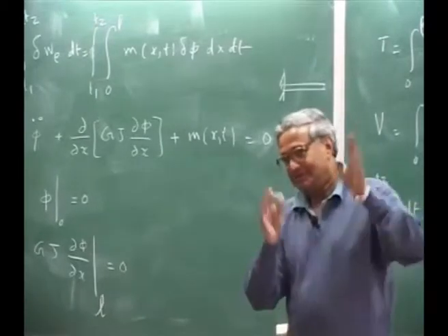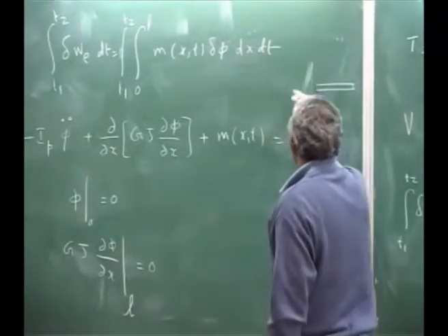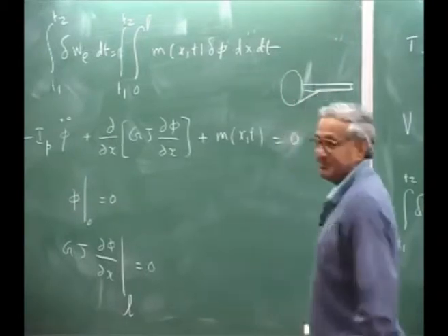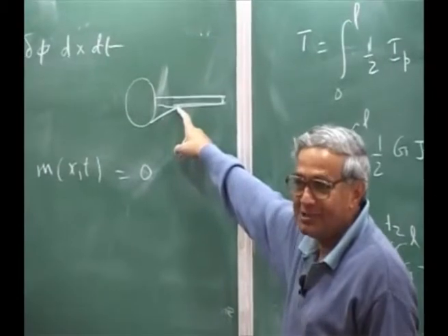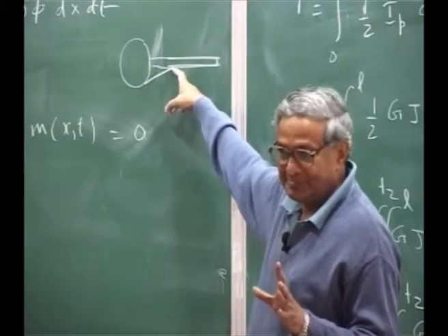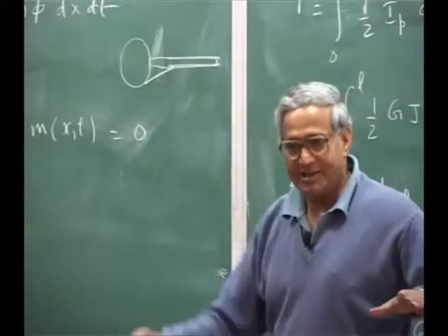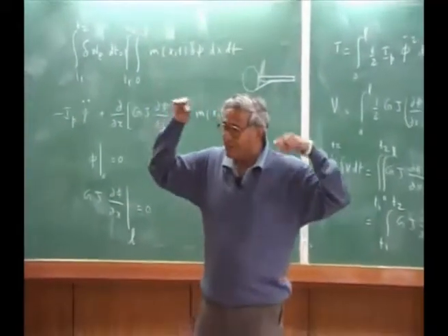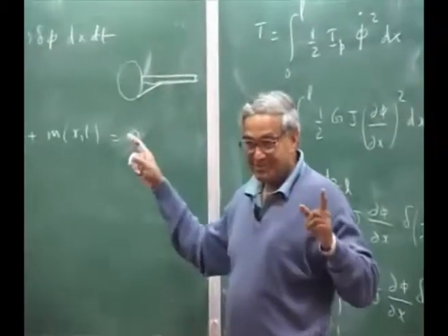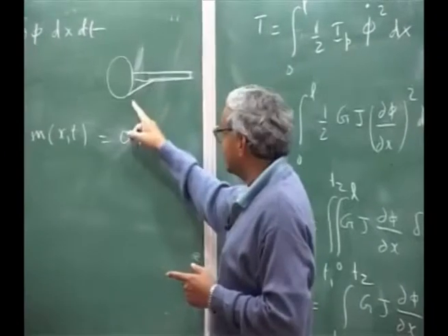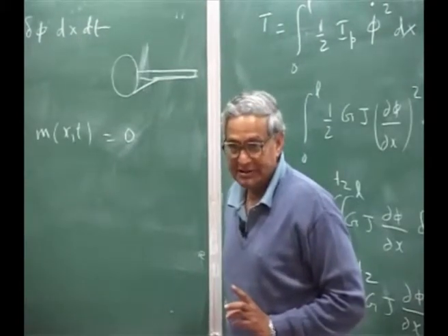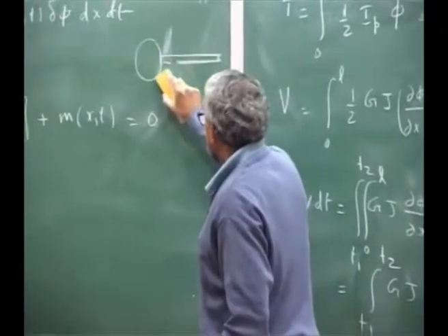Suppose you say, I am just going a little further. You may have some problem like this. In an aircraft, old aircraft, you are supporting by some structure here, somewhere in the middle. Okay. Then how will you model this? See, all these problems you have to pick, because you are modeling. Today everything is a cantilever beam, all the wing structure. In the old days they put a strut and then attach it. That means there are two ways. One is you can break it into two parts of the beam and then match the boundary condition there. Or you can say this is like a delta function, which is an external load which acts at that point, additional external load.